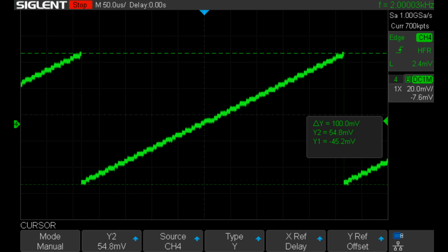And here's a 100 millivolt peak-to-peak rising sawtooth. So I think I'll end here. In summary, I think that the M2K is not all that great for producing and viewing very small signals. You might consider yourself limited to 50 or 100 millivolts peak to peak.